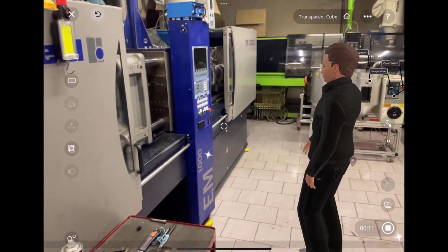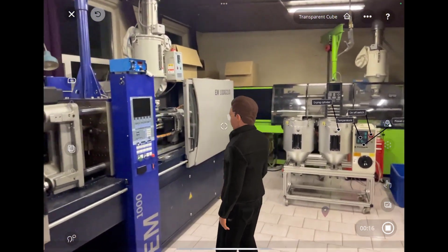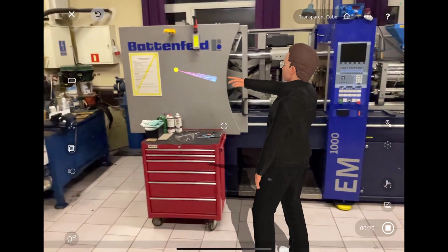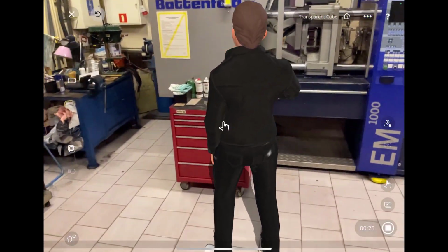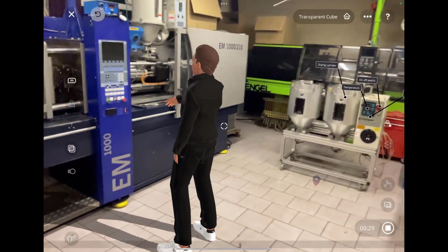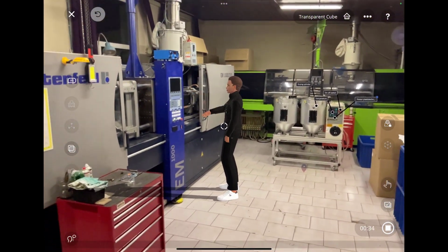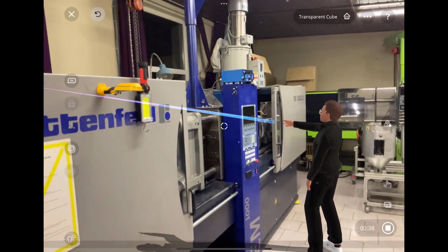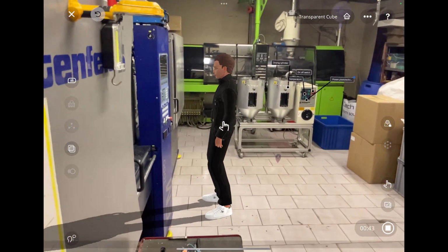We have a control panel, on, emergency exit, emergency stop button. There is a mold inside it already mounted. Health and safety instructions. Also, we have health and safety equipment in here, like a glove, toolbox with all the necessary tools. Via the control panel, we're setting up the machine, making sure that everything is clean and ready for plastification, preheated. The plastic injection material will be supplied for a plastification process inside this tube.